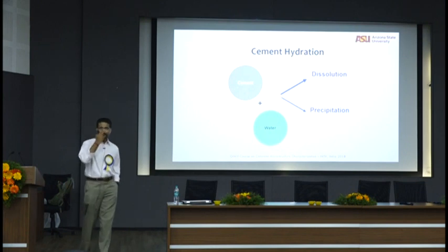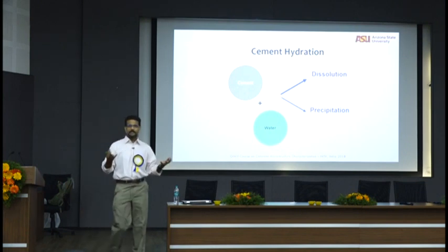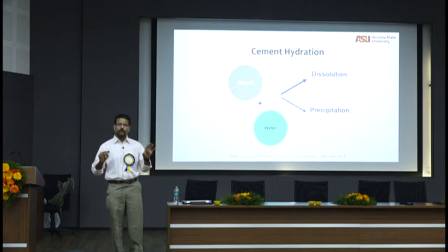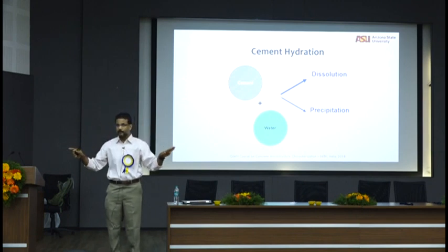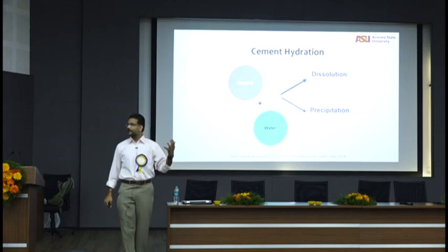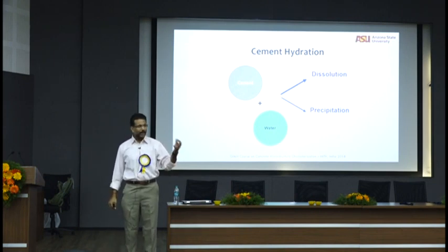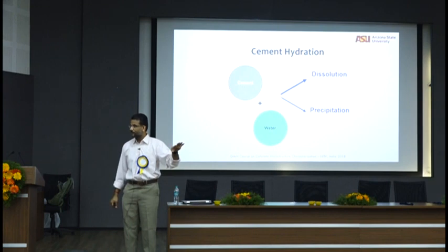Two different things happen when cement reacts with water. Again, this is the core of microstructure formation. So let's not think about too many cement particles. Just think about one particle of cement in an infinite ocean of water. That's easy to understand. We call it an infinite dilution. One particle, as much water as it can take to react. So there's no competition, no fight between particles for water, right?